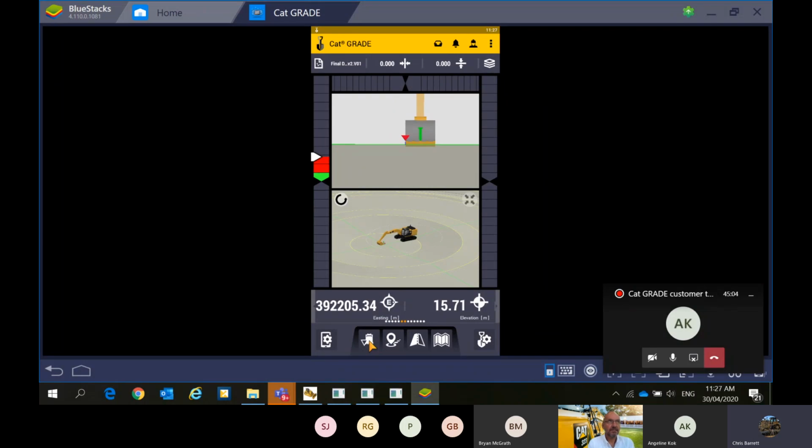So when you're checking to make sure you're getting the right point, make sure you've got the focus point selected on the side of the bucket that you're actually putting on the control point. Fantastic. So it's fair to say that if you're using a tilt hitch, that's where you would need to change that focus point, right? Yes, and that's a good way to check the bucket accuracy on a tilt hitch. We'd put it on the right hand side, swap across to the left hand side, and double check both sides. That's going to make sure that it is accurate.